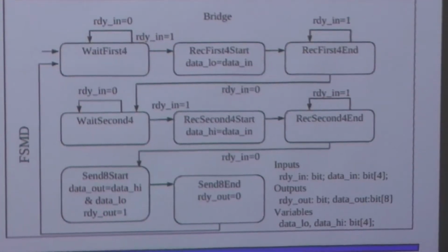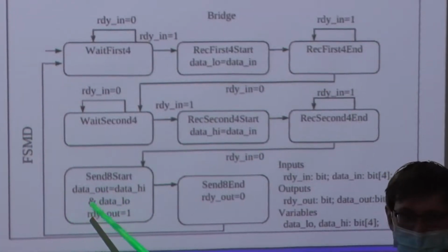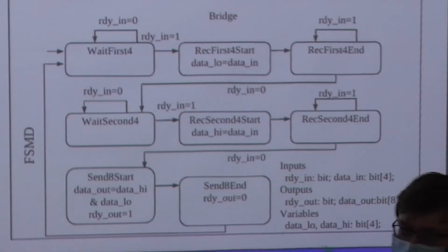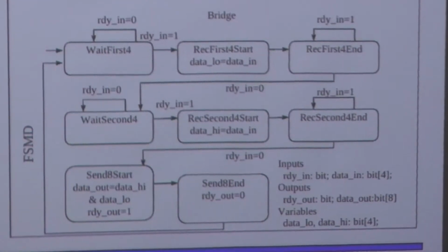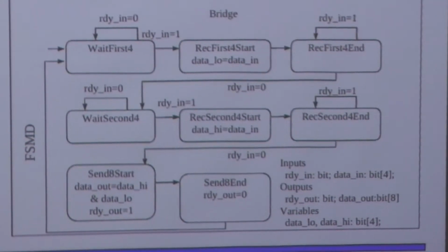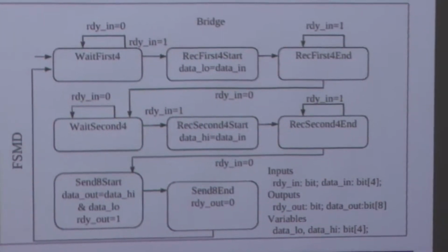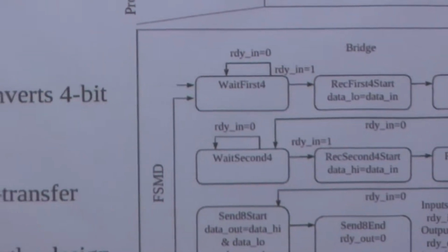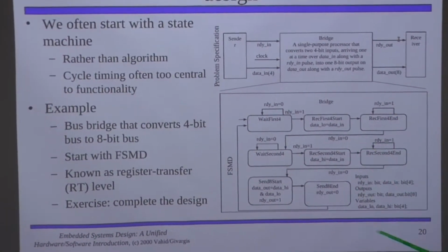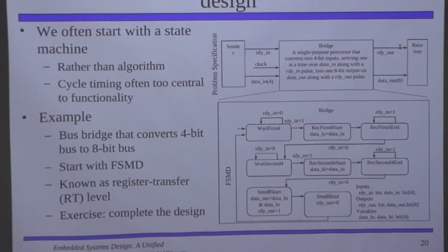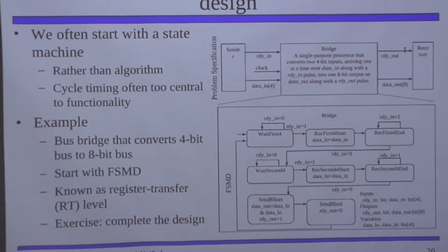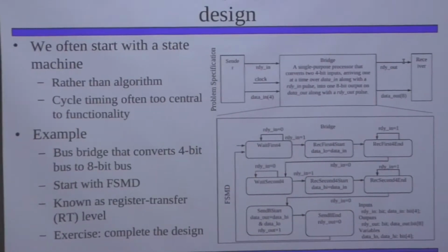I guess AND just kind of stands for bit concatenation for some reason here. And I don't actually think that it would be useful to do bitwise OR combined with a left shift operation, because that's too much. Frankly, I don't even think you need a register here. You can probably just serialize or parallelize the 2 registers' output lines, and there you go. I'm not sure that the 3rd register is even necessary, but again, this is not an optimized design, and we shouldn't criticize it too heavily.